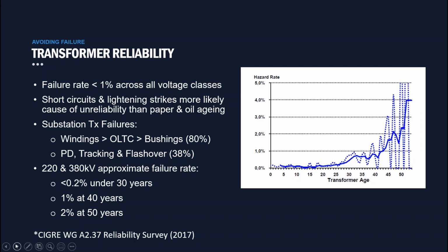And recently we worked on a 25 MVA transformer that was struck by lightning. So the winding was damaged, and we had to do a full rewind for the customer at our transformer manufacturing facility in Newcastle. In substation type transformer failures, the main locations of the failures are in the windings, in the tap changer, in the bushings. And in my next presentation, in a few months, I'll be talking more about on-load tap changers.